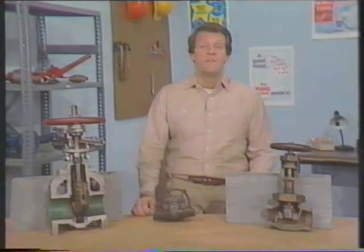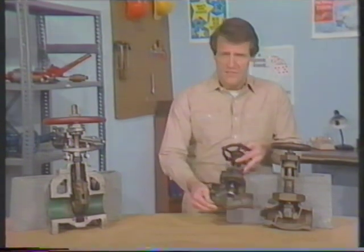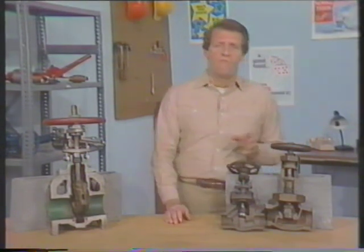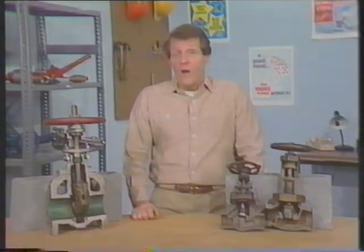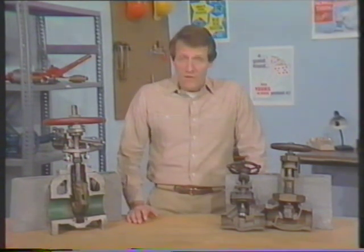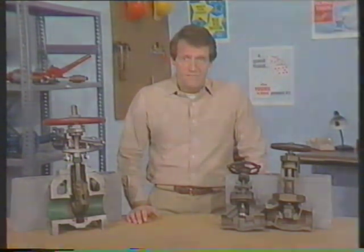Well, now you've seen the operation and some of the uses of gate valves, globe valves, and some variations of globe valves. You've seen why gate valves are typically used in fully open or fully closed positions, and why globe valves and needle valves are especially suited for throttling. When we get back, we'll look at several valves that may be used for either on-off or throttling purposes.